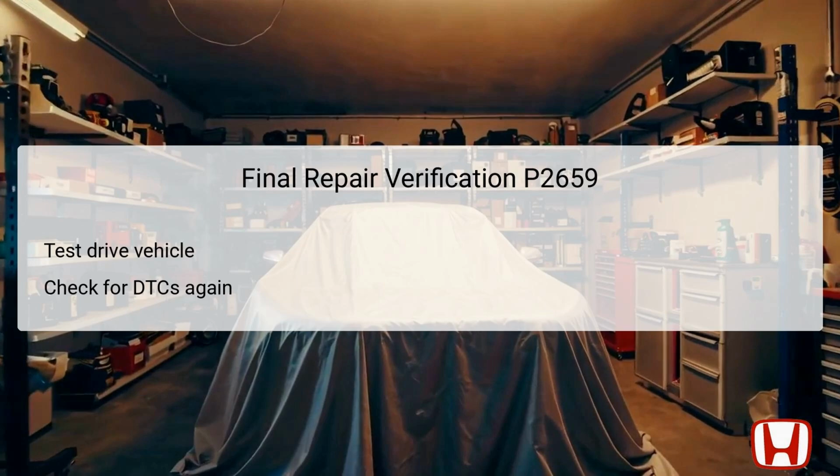Once all previous troubleshooting steps are completed and appropriate repairs are made, a final verification is essential to ensure the issues have been resolved. The technician should conduct a test drive of the vehicle to assess its operational integrity and performance under normal driving conditions. After the test drive, it's vital to check the vehicle's diagnostic systems again for any lingering or new DTCs.